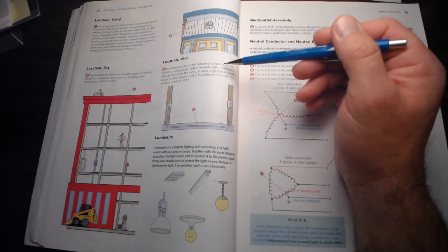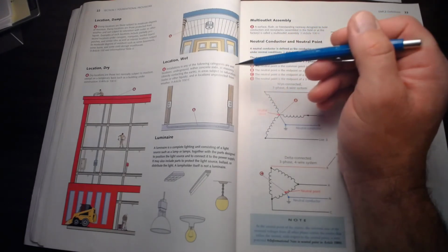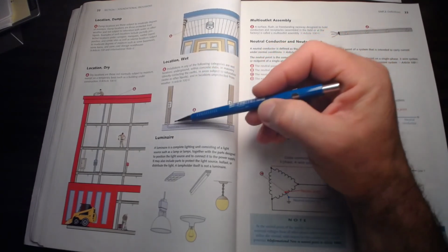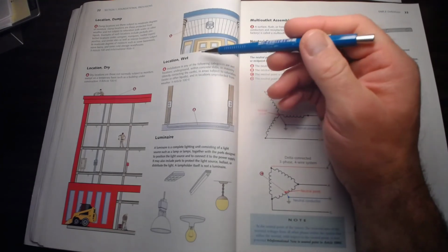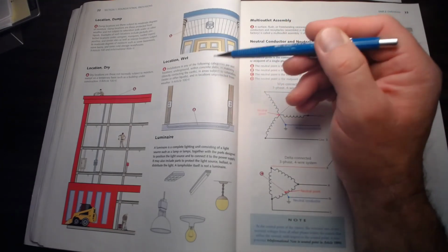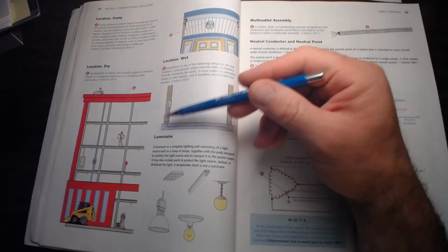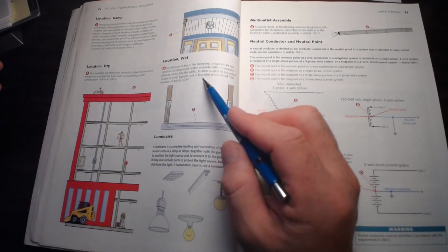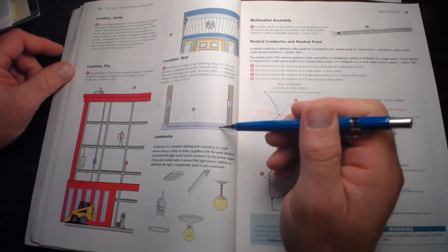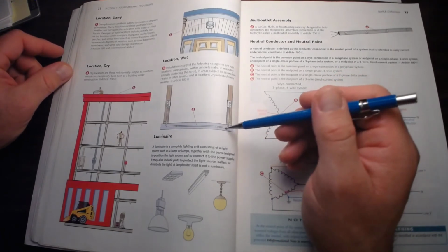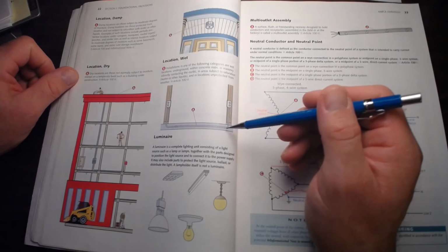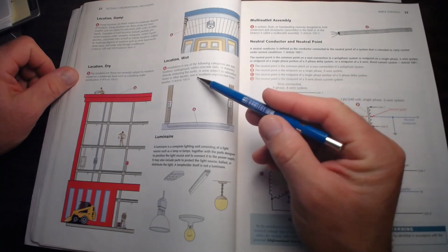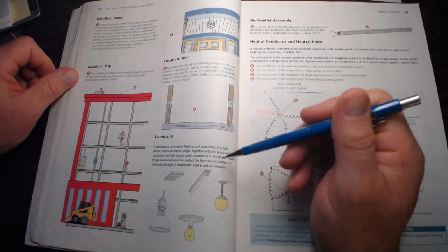A wet location is an installation in any of the following categories. Underground: there are usually underground conduits that fill up with water, so that's easily a wet location. Within concrete slabs and masonry, there's condensation that's going to be in these conduits, so it will be a wet location. In areas subject to saturation of water or other liquids, such as a commercial kitchen or food processing area where you have to hose down the area, that's considered a wet location. In a bathroom where your receptacles are close to an outlet by a pool, they are going to be a wet location.